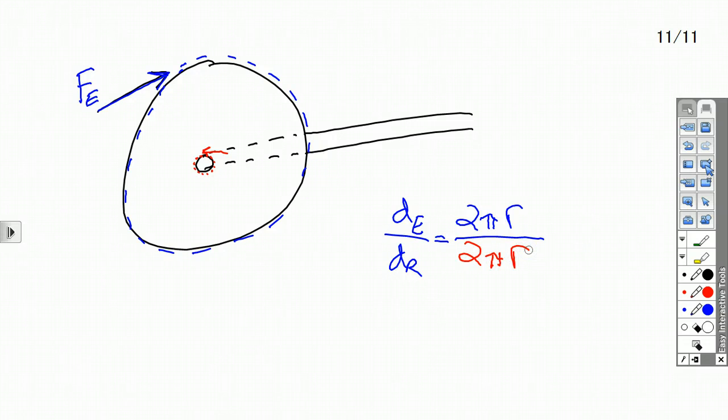So you're looking at two radii. The radii for the effort, where effort's being applied, and the radius for the resistance, where that's being applied. If you notice, these two pi's cancel out. So even though technically we're looking at circumferences, we end up able to compare the two radii that we're looking at, or the diameters, it's just twice the radius. We end up comparing those instead.